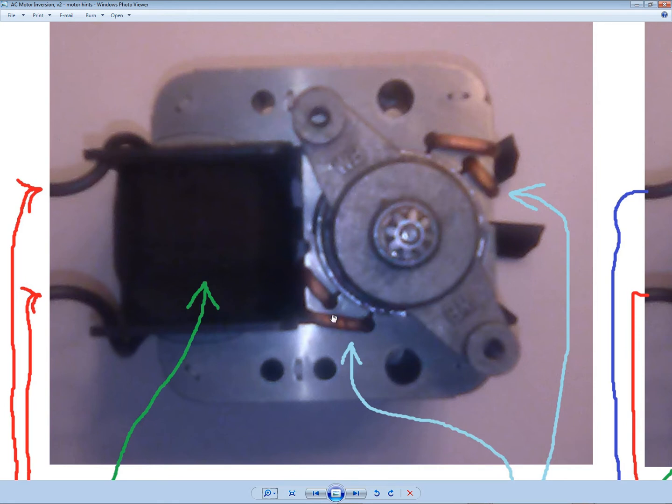Well, these are the starter coils. What happens is the AC comes in here, that's what these red arrows mean. The AC current comes through here, 120 volts, 60 cycles, and all it does is get the squirrel cage to wiggle back and forth, to jiggle, first clockwise and then counterclockwise, and it jiggles every half cycle of a 60 cycle. So 120 times a second, it changes direction. If it were not for this pair, they are called starter coils, that's all that would happen.